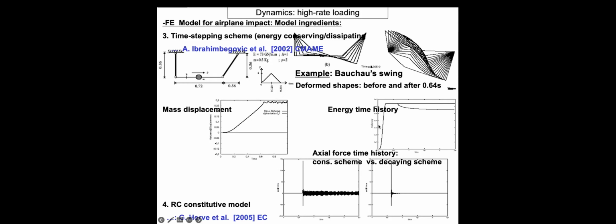Now if we use the energy conserving scheme, you can see that after the loading stops at 0.3566, you can conserve the energy fully. But with the energy conserving scheme, after this 0.64 second event happens, you basically enter into axial deformation, and your stress computation becomes quite meaningless because I think we put only 8 elements.